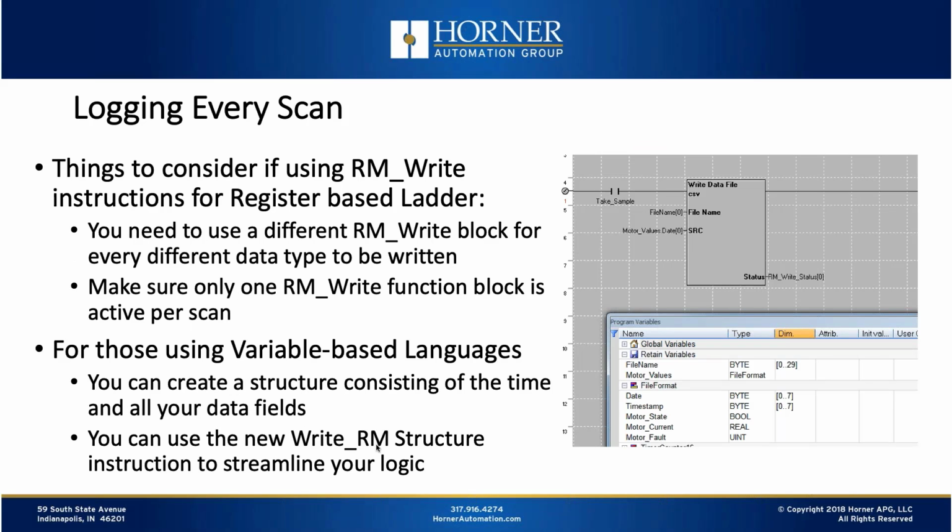Now, if you are logging every scan, there are some things to consider when you're writing this logic. If you're using register-based ladder, then you need to think about the fact that with the removable media write block, for every different type of data that you're going to write from column to column, you need to have a separate write function block. Okay, so that is something to manage. And you also have to make sure that in your logic, only one write function block is active per scan.